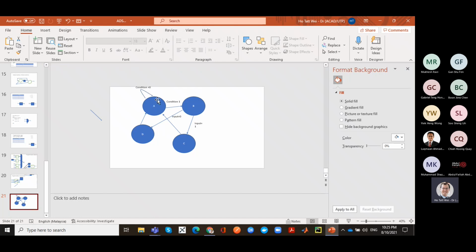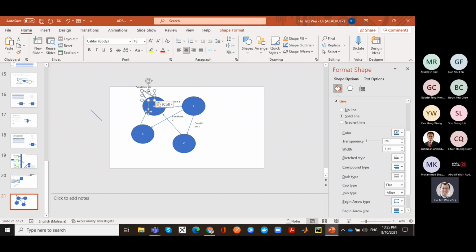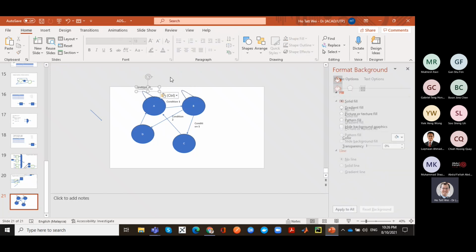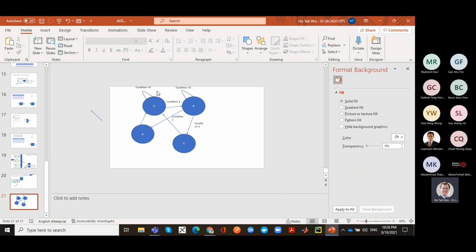You take how many clock cycles, and when you want to transition to the next mode, a condition has to be fulfilled, right? And so here is also the same condition, except that here maybe you have condition 1 and you have condition 2. It doesn't have to be a binary condition, it could be a multi-bit condition, right? So if you have condition 0, you might actually still retain or remain in that particular state. Okay, so the most general state transitions are something like this.